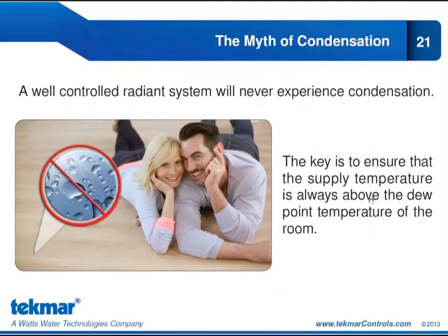If our target water temperature was ever to be below that dew point, it would automatically be adjusted. And that's something we call dew point reset that we'll talk about more throughout this course. So we always make sure that our supply temperature is above the dew point temperature of the room by at least 2 degrees.